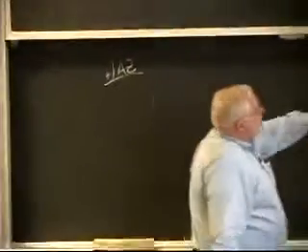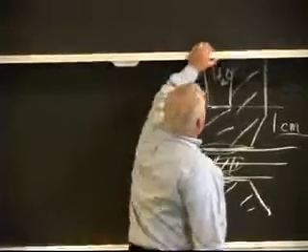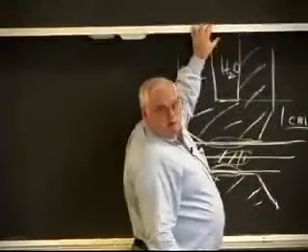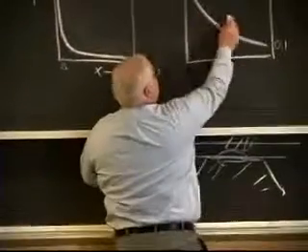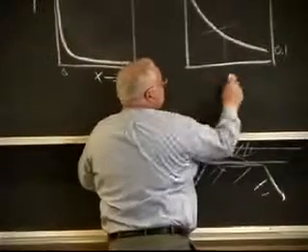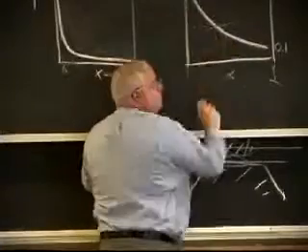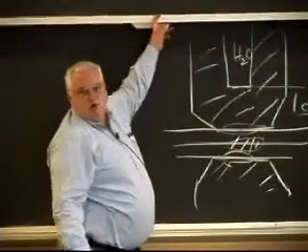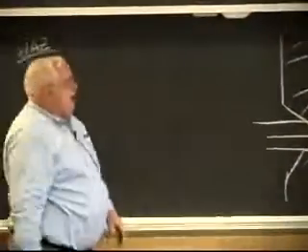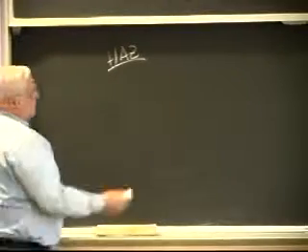Well, the heat affected zone size is somewhere where the Fourier number is equal to 1, where I've heated the thing up to some distance. If this is X and I heat it up to some intermediate temperature about halfway in between, that's when the Fourier number is 1/2, if you want to use 1/2.